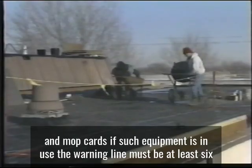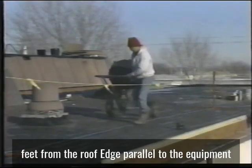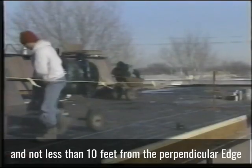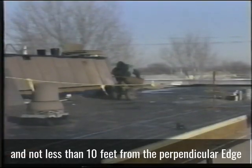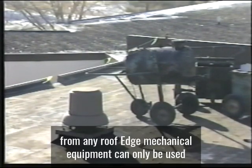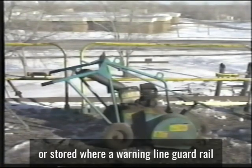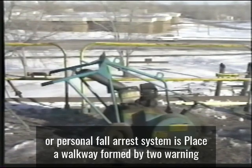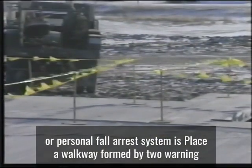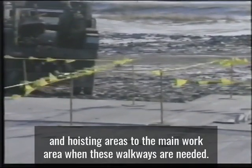If such equipment is in use, the warning line must be at least 6 feet from the roof edge parallel to the equipment and not less than 10 feet from the perpendicular edge. When mechanical equipment isn't being used, keep the warning line at least 6 feet from any roof edge. Mechanical equipment can only be used or stored where a warning line, guardrail, or personal fall arrest system is in place.